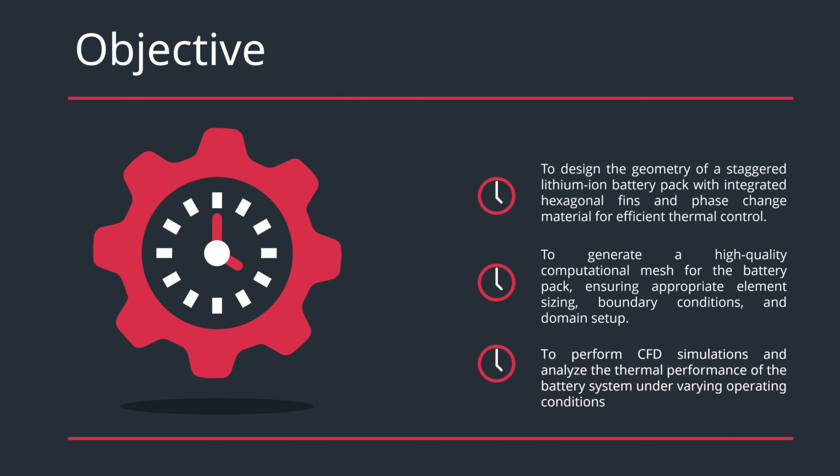So the first objective is to design the geometry of staggered lithium-ion battery pack with integrated hexagonal fins and having a phase change material for the thermal management. Then generate the high quality computational mesh for the battery pack, ensuring the appropriate element size and boundary conditions, which is required to be done in the setup part. Then perform the simulation and visualize the contours of liquid fraction, contours of total temperature of the system, and so on.